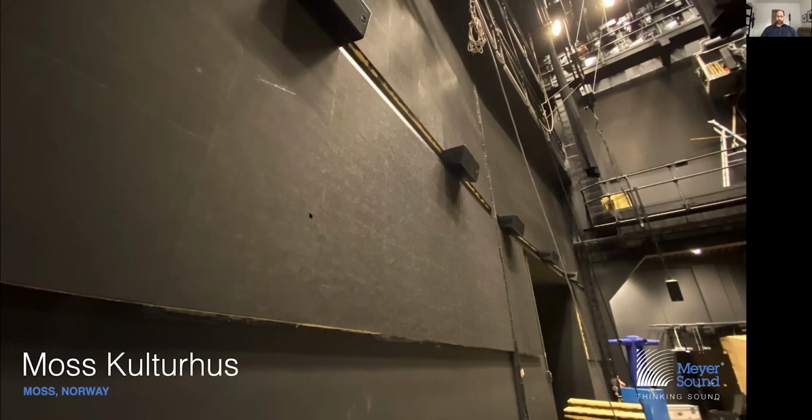We generally prefer anywhere about NC 25 to 30 is what we target. And we've had some instances where there might be a large return air vent on stage that makes a really loud noise, and that obviously will get picked up by the microphone. So the HVAC sound control is really important in addition to the reverberation time, especially on stage, since that's where the microphones are, and it's going to be broadcasting that sound throughout the entire auditorium.